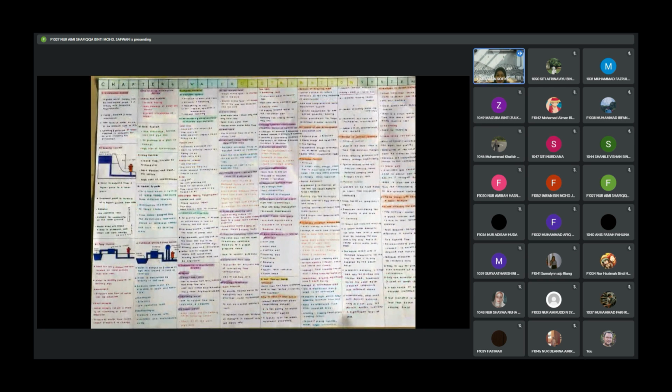Chapter 4 is about water distribution system. There are 3 types of distribution system, which are gravity system, pump system, and combined gravity and pump system. For water distribution system, there are 4 systems included, which are dead end system, grid system, ring system, and radial system. Next is piping material. There are 3 main points, which are selection factors, advantages and disadvantages of multiple pipe material, and selection of pipe size. Next, components in distribution system. There are 2 components, which are valve and storage reservoirs.